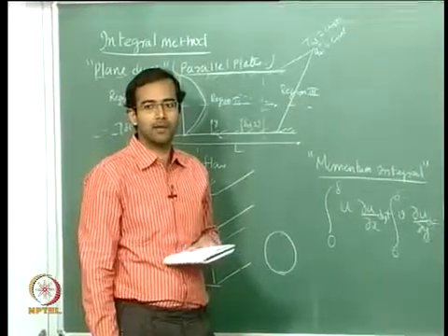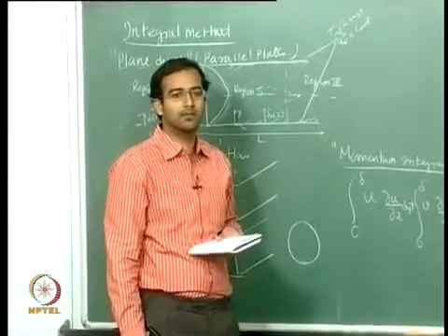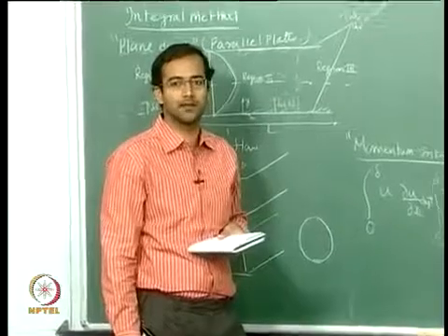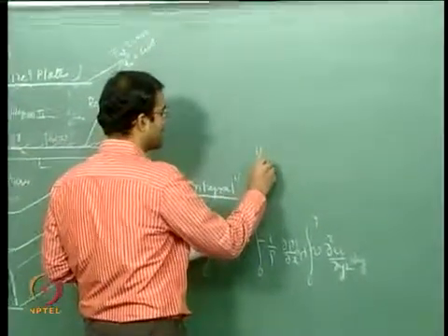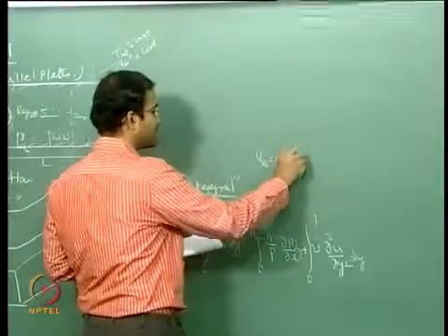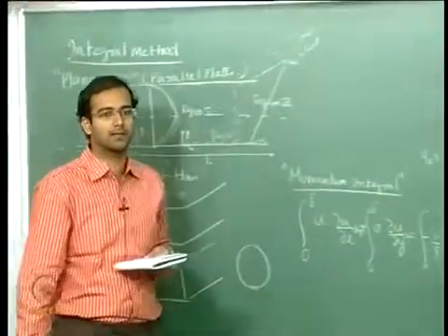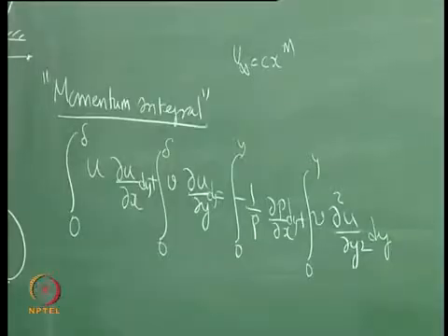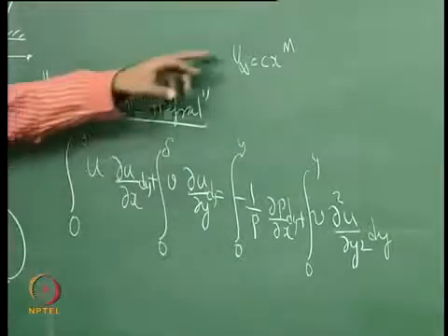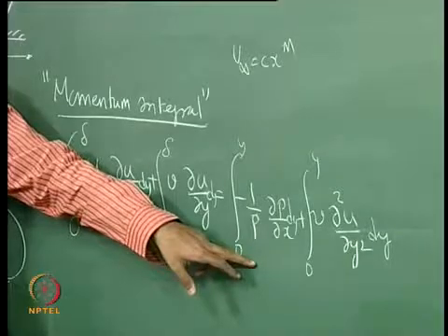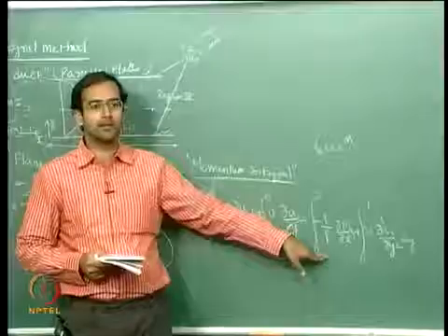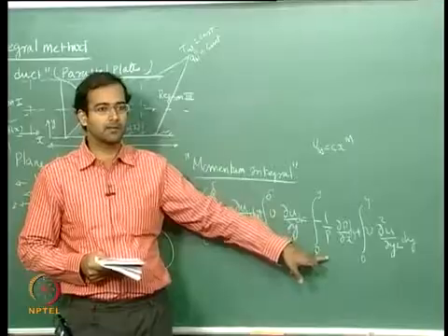So when you have a pressure gradient term, you should know how the free stream velocity is varying. So for example, in the external flow case, you took free stream velocities which are varying of this form. This is the Falkner-Skan kind of a profile. So you should know what is the variation, and then you can substitute for dp by dx as du infinity by dx. However, in the internal flow case, it is not very clear about this.